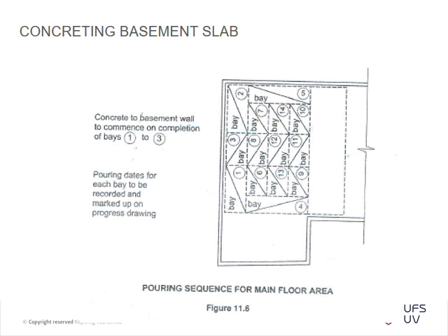Remember that site visit where we had the construction joints and the saw cut joints for the expansion or movement of your concrete. That's basically why you have to plan the boxing in of your concrete pours within the specified parameters from the contract or engineer.